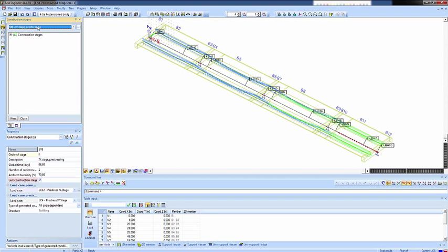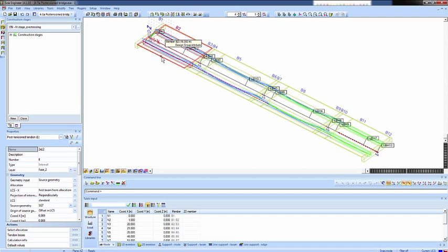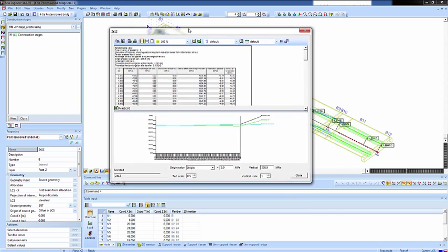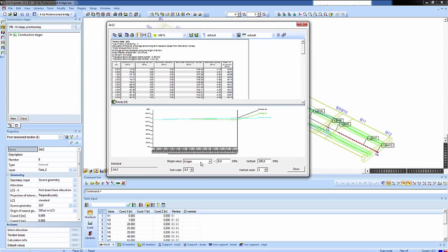The immediate losses to which I referred can be viewed when you select this tendon. For example, if I pick this tendon, I can immediately see what my tendon losses are. It will show you my tendon losses. The image might not be clear, so I will up the text scale. You can see friction losses there.